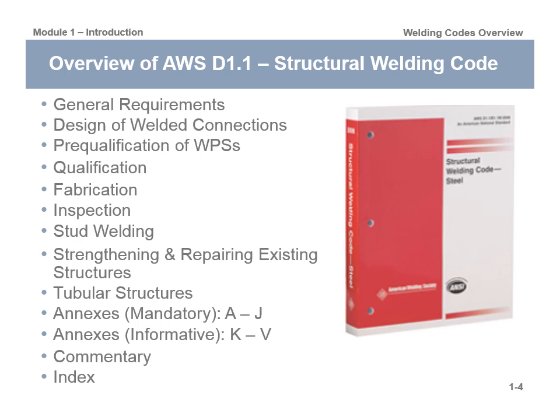Clause 7 is stud welding. Studs are generally on components if you're going to need to hang something, or the more probable situation is a stud for concrete, so you could tie a steel structure and then pour a concrete deck on it or something like that. Strengthening and repair of existing structures is clause 8. And then they've kind of changed things from previous years. I think the way that the code was written, everything was too messy with tubular structures in with everything else. So they added a clause 9 with tubular structures.